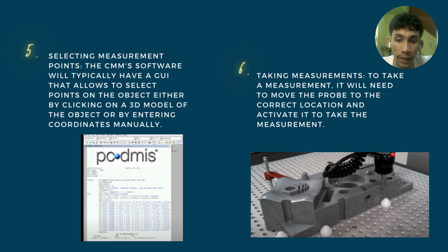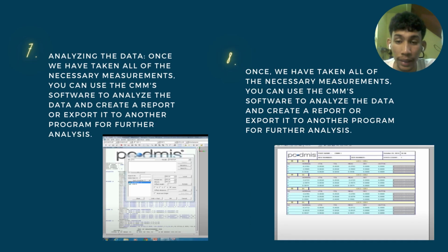The fifth one is selecting measuring points. The CMM software will have a guide that allows you to select points on the object either by clicking on the 3D model of the object or by entering coordinates manually. So the sixth one is taking measurements. To take a measurement, you need to move the probe to the correct location to take the measurement.